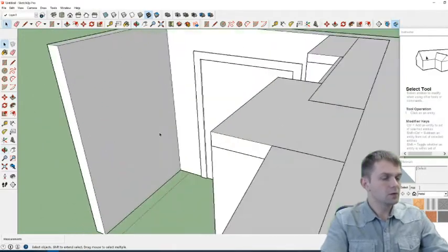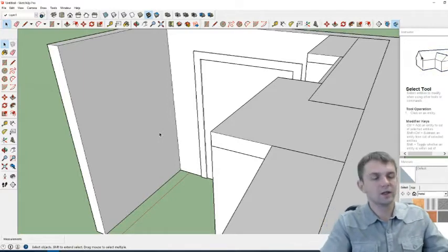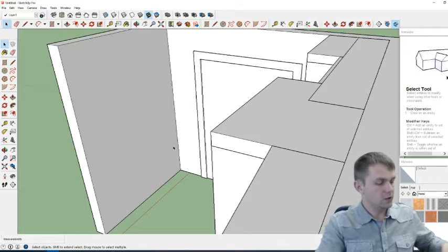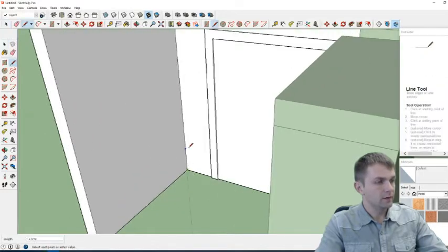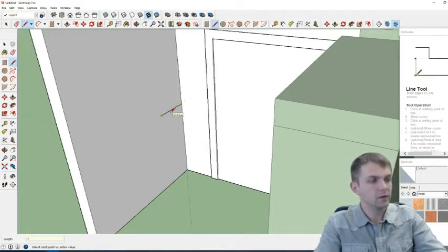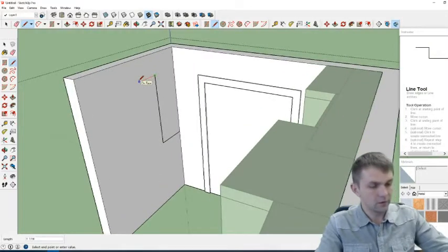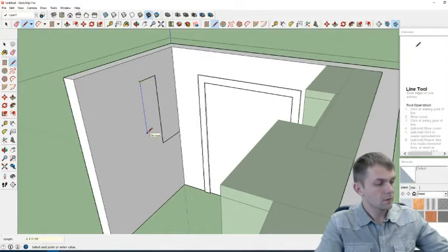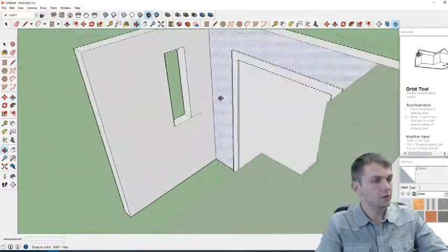Now what they want to do on this wall is create these kind of interesting niches, little skinny niches with the LED lights. They weren't sure how that was going to look. So again, I have to edit this wall. I triple click the line, and it's about 42 inches tall. It's giving me a green light, 17 inches. Then it's about 42 inches tall, and it's about a foot. 42, and I go pull, and I just click the end, so you have a niche.